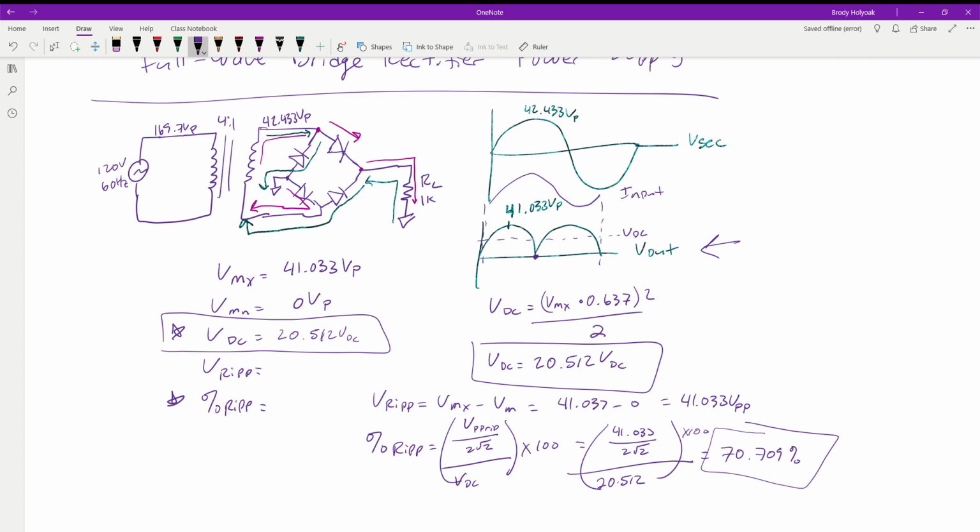Now, the way you can determine if the circuit is filtered or unfiltered is it has to have some sort of a reactive component, like a capacitor or an inductor. And in this case, we're using the inductors as a transformer, so that's not taken into account, because that inductance is already basically being canceled out and utilized in the transformer part. So we don't have to worry about that. But the idea is we have a filter that we create by using a capacitor, because a capacitor builds up and stores a charge on itself that it can use later to power the signal.